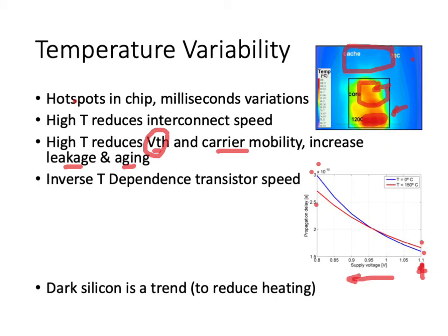Whereas in the case of the low supply voltage, we're talking about a lower headroom, so changes in the threshold voltage become significant. At a lower supply voltage, if you reduce the VTH a bit more, the increase in current due to the lower VTH outpaces the decrease in carrier mobility, and this is what you are seeing in this situation here.